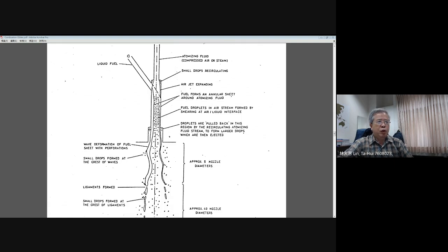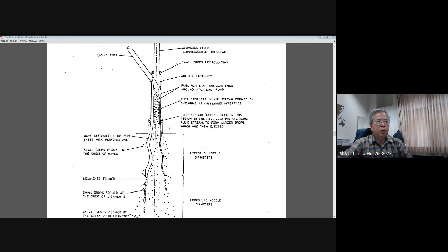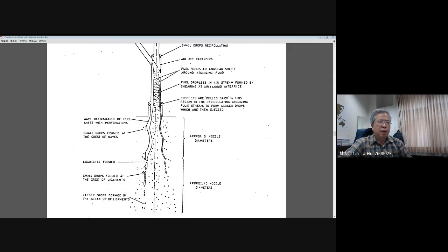Finally, when they impinge out, the liquid follows the surface of the injector and produces the spray cone. And you can see here this wavelength occurs and breaks up into the ligament. Because we take a cross section, you need to figure out this cross section of a donut shape, and this is a ligament. And this ligament is further broken up into droplets.